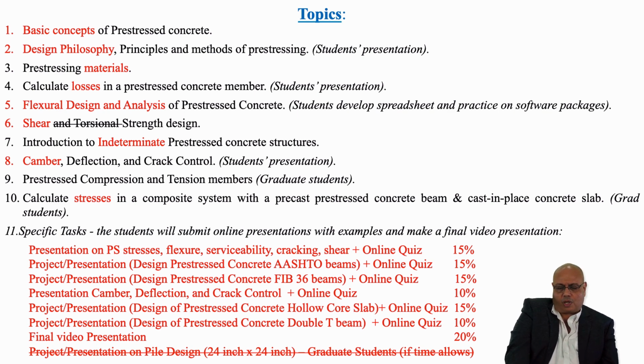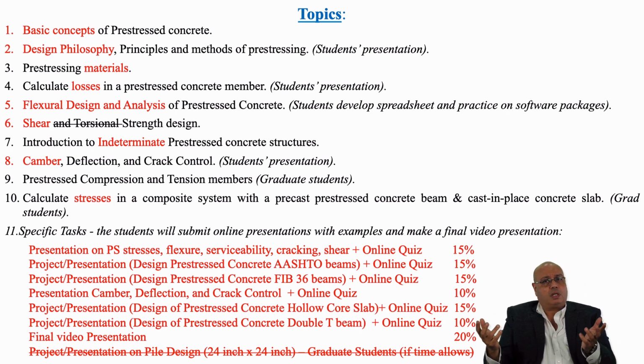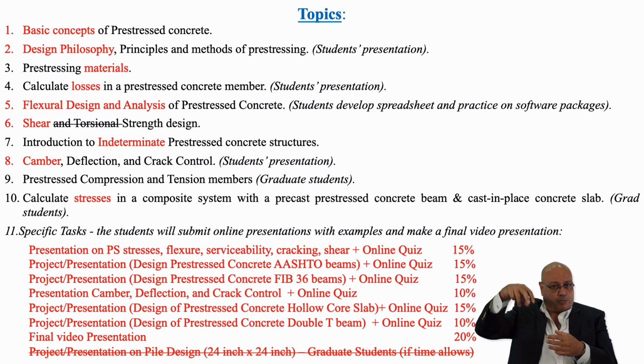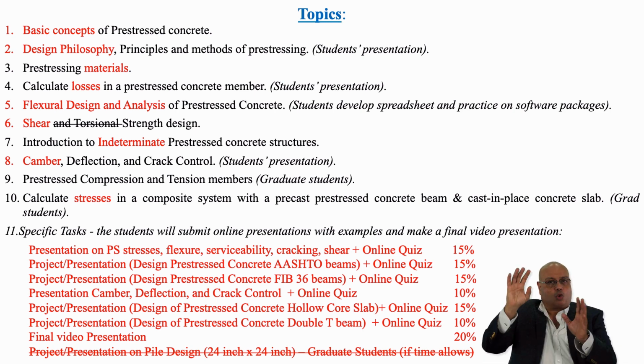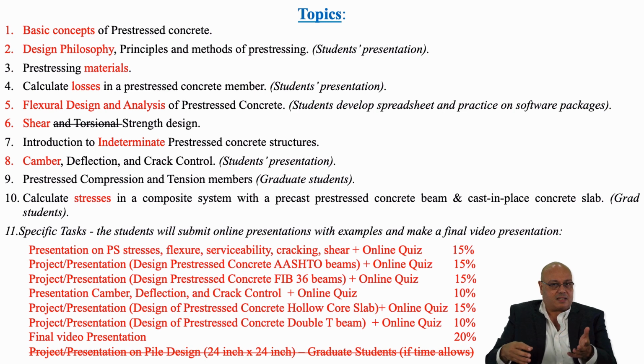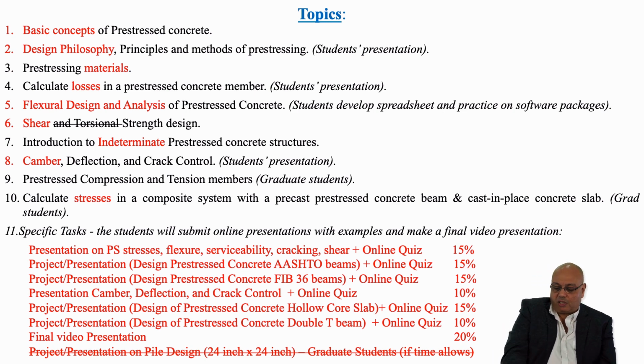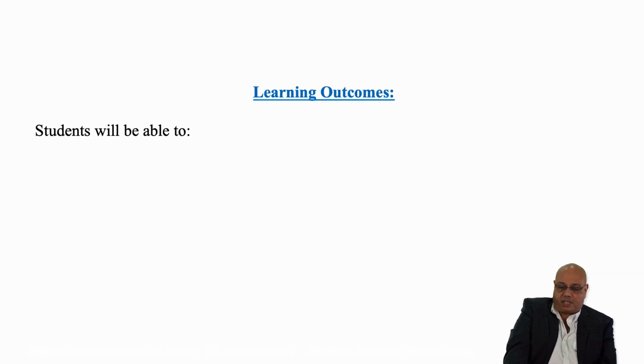It's a very interesting project for a reason. Of course, you know why we're using carbon and glass instead of steel. Do you guys know why? If you have buried structures, buried concrete in the soil, and something happens to it, like corrosion and sulfate attack, corrosion primarily is the one that's attacking the steel reinforcement. If you have glass or carbon, it's a non-corrosive material, so you don't have to repair, because there is no repair for that. It's going to be just primarily replacement of the piles.